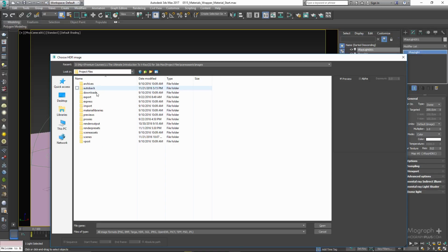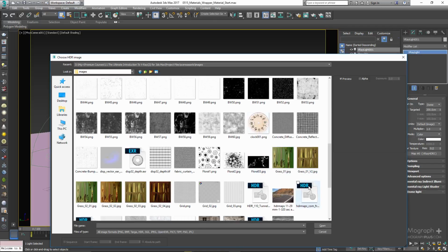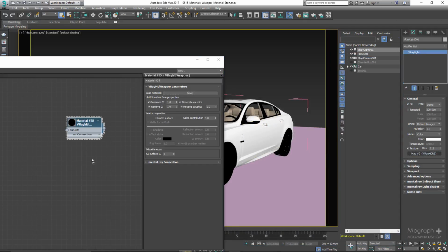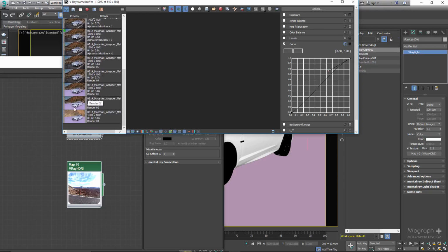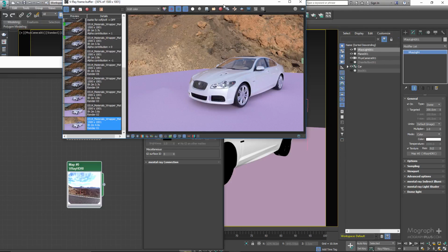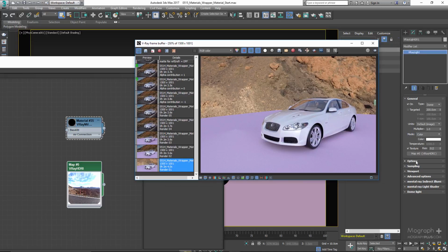And also let's open up the material editor and drag the HDRI map to the active view. If we render the scene right now, the result would be render 01. We really don't need to see the HDRI image, we just need its lighting contribution. So in the options rollout of the light, let's make sure it's invisible.